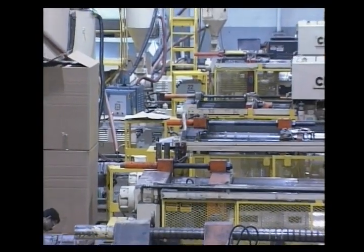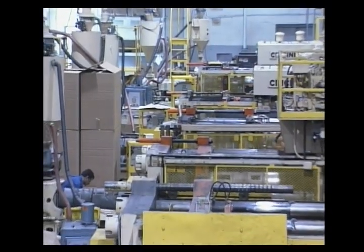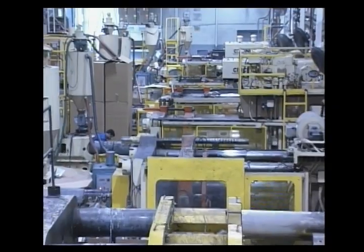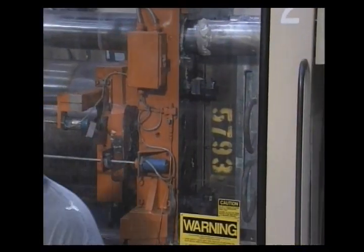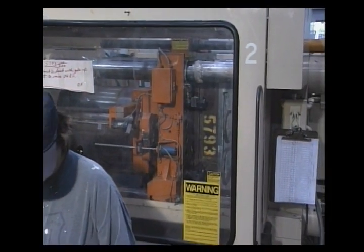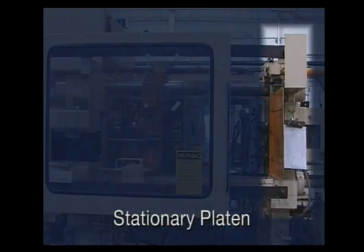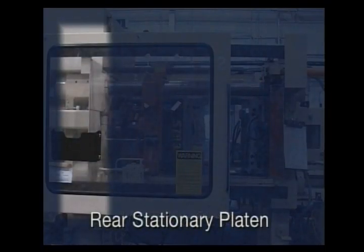Injection molding machines are designated by their clamp tonnage, which is the amount of sealing force a machine can produce against the high pressures generated during the injection process. Platens are large, thick blocks of tough steel which will not deflect enough to affect the injection process. There are 3 platens on most injection molding machines: a stationary platen, a movable platen, and a rear stationary platen.